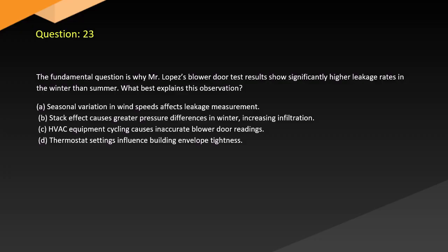Question 23. The fundamental question is why Mr. Lopez's blower door test results show significantly higher leakage rates in the winter than summer. What best explains this observation? A. Seasonal variation in wind speeds affects leakage measurement. B. Stack effect causes greater pressure differences in winter, increasing infiltration. C. HVAC equipment cycling causes inaccurate blower door readings. D. Thermostat settings influence building envelope tightness.